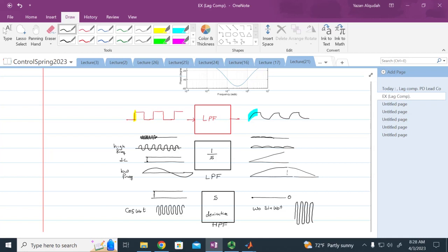So you see, if that signal is constant, there are no changes, and the high-pass filter removes that signal. If there are changes between a value and the previous value, the high-pass filter, or the derivative, will amplify that difference. Make sense? Okay, so keep that in mind as we look at the different compensators, because it will help you better understand how these compensators are working.